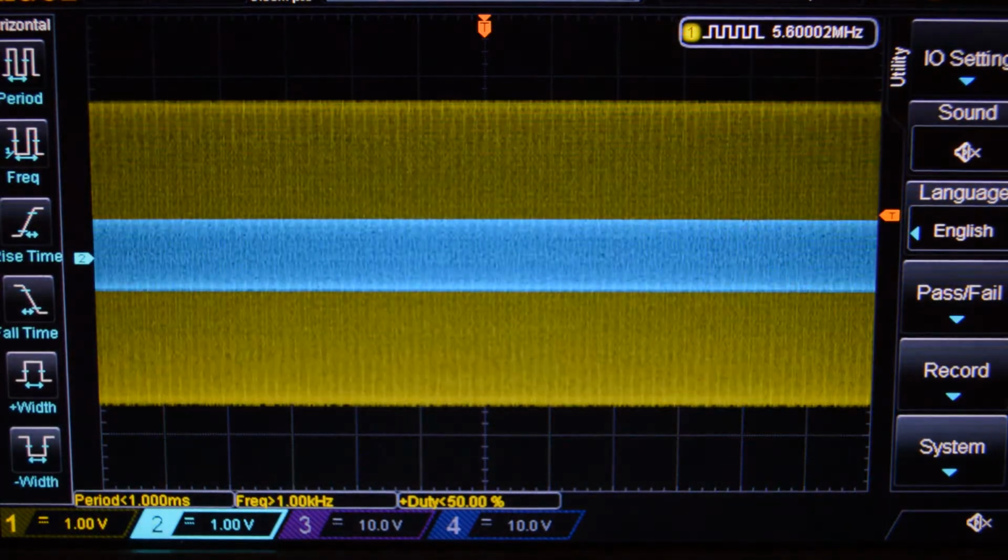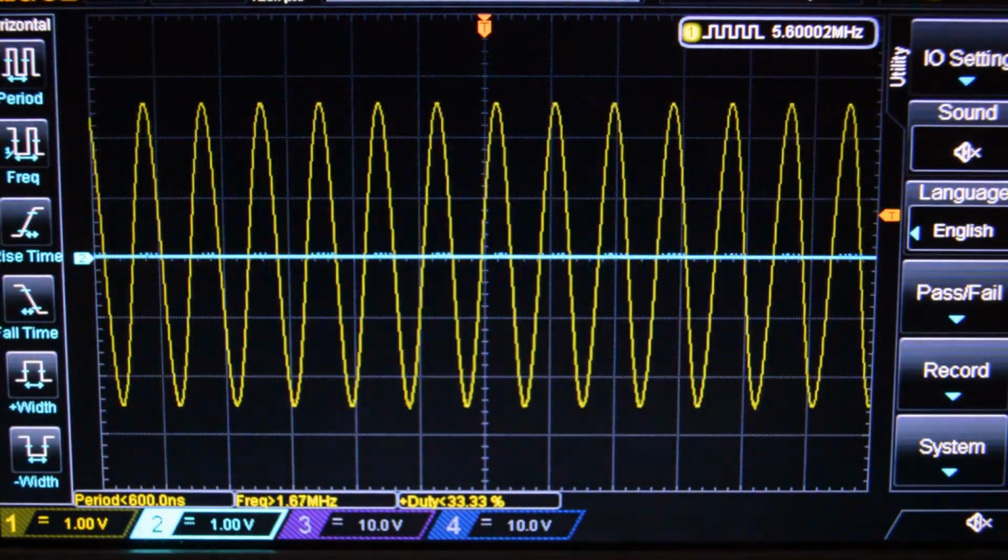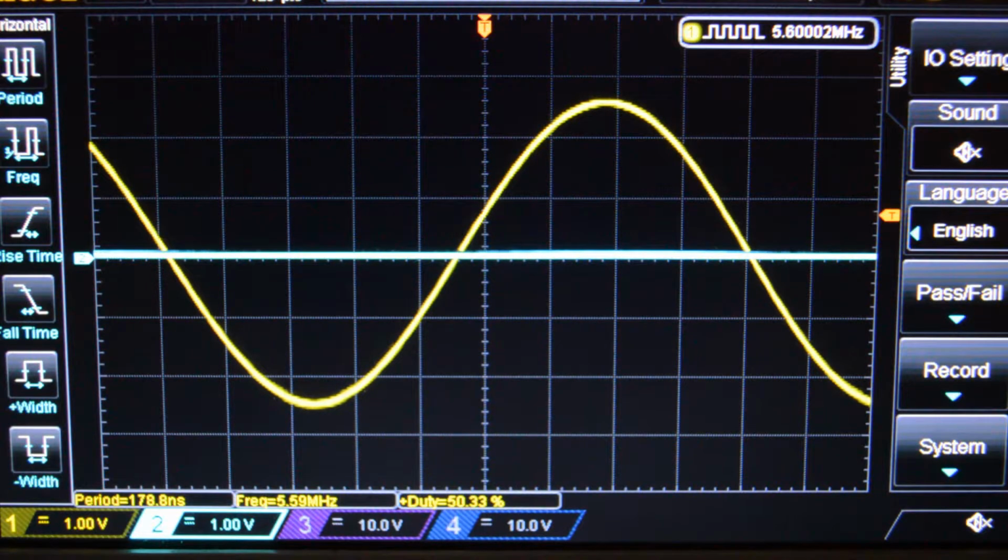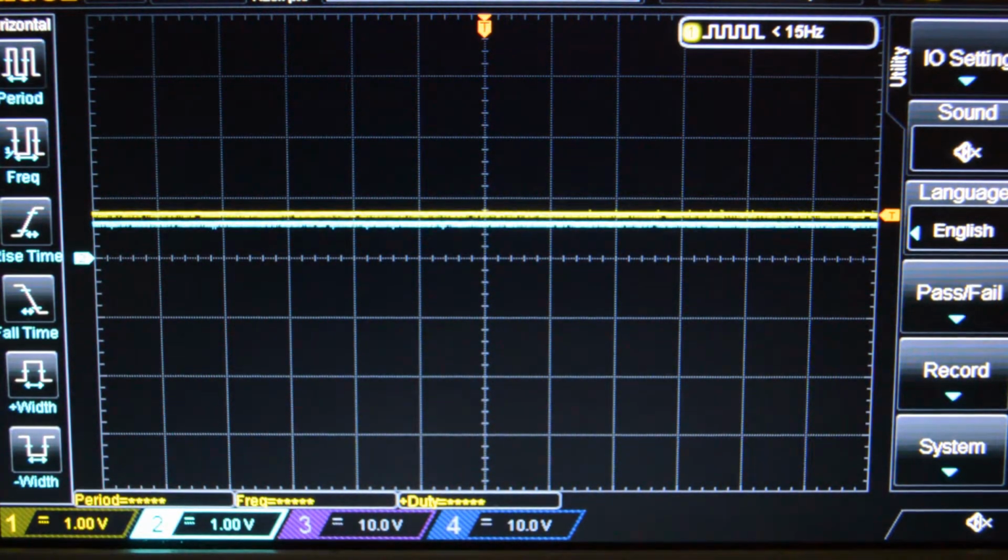So that's really interesting behaviour. At low frequencies the output is pretty much the same as the input, but at high frequencies the circuit blocks the input. Now let's run that sweep again and consider the approximate equivalent circuits to help us understand what's happening.